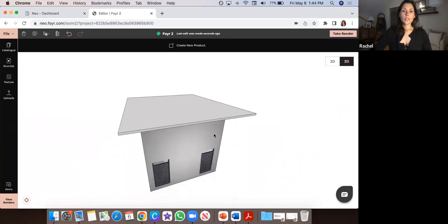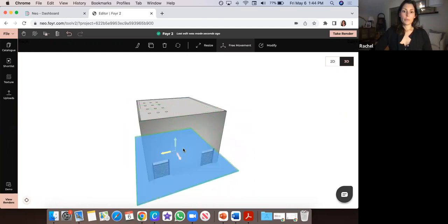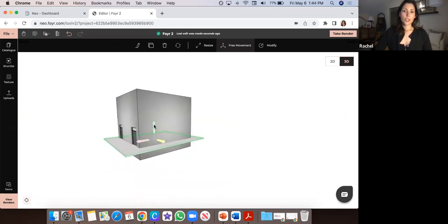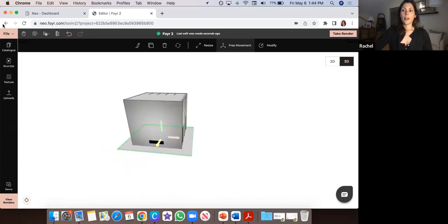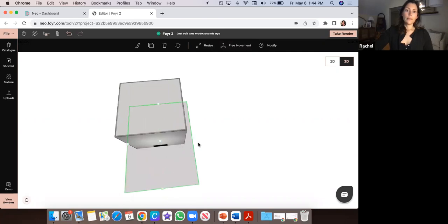You can also just resize this in 3D mode because it's just a simple shape. That's just object snapping, highlighting blue, wanting to help me out. It gets frustrating if things are snapping and you want to have total control. Feel free to turn object snapping off under the file and settings like I showed you earlier. So here we are. Now it's under there. I'm going to click on resize now and just bring it on out. Either or.